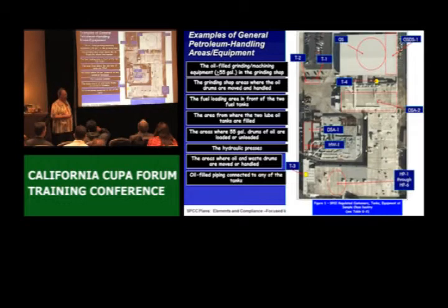So for a 25-year storm event, in the past people typically used just 10% of the total size. The adequate freeboard, no. For sized containment there has to be sufficient capacity for 100% of the contents of the largest container or compartment plus adequate freeboard for precipitation. Who determines adequacy? A registered professional engineer. Commonly, 24 hours of a 25-year storm for that region. Oftentimes they'll use 110%, whatever they determine to be adequate. More and more, it's going to 24 hours of a 25-year storm.